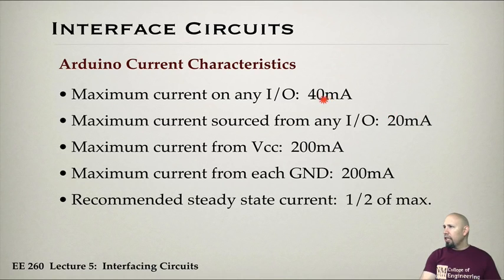If you have that digital pin and you ground it, it's set to low, so it's ground. It can actually take in 40 milliamps from whatever its source is. So basically, you can sink more current than you can source. That's why it's very common, when you want to turn on an LED, to have a pull-up resistor from the LED, because when you set the pin low, then it acts like a ground and it can sink plenty of current. Okay, so that's important.